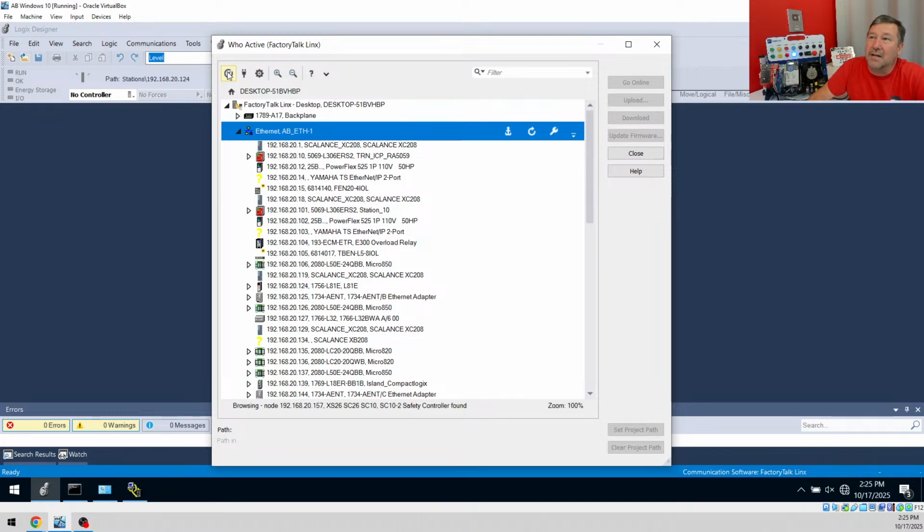Now, incredibly important, this first icon, because I'd actually done it in RsLinx and I saw it. This is the auto browse. So see these boxes marching right here? This is super important, these boxes. But if we accidentally check that box or uncheck that box, or take it from semi-yellowish to not yellowish, notice they are not bouncing now. They're not marching. And if that animation is not happening, this list will not be updating. So you'll go in and try to connect to something that's not there, or you won't see something, and it's because somebody's accidentally hit this button. So we want to make sure that it looks kind of yellowish.